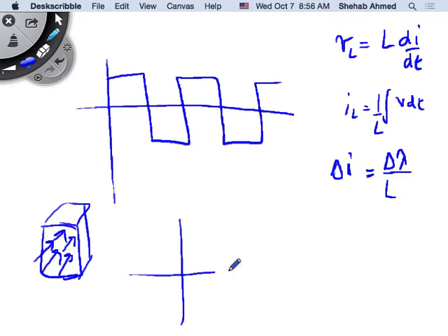Remember the BH curve? You've reached the saturation point. So H is proportional to I, right? H is equal to Ni, right? The magnetomotive force is basically proportional to the current that you're putting through. So if you keep increasing H, which is keep increasing I, you're not getting any more magnetic flux. You're not able to, because the core is saturated.